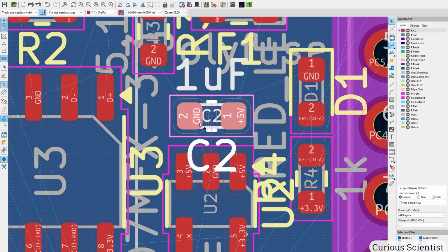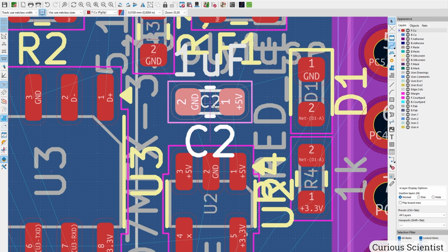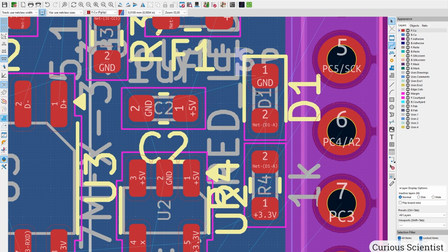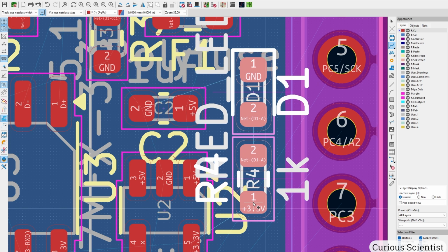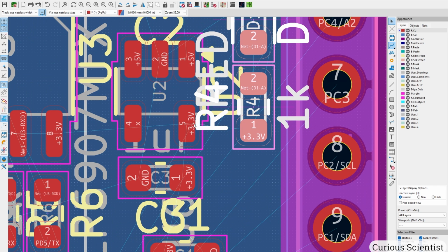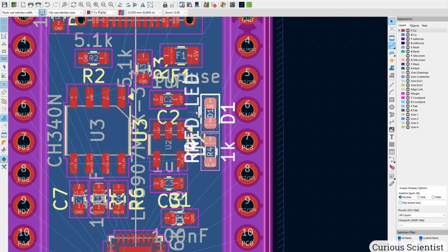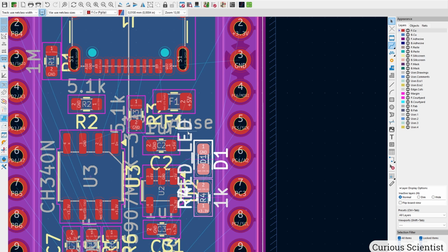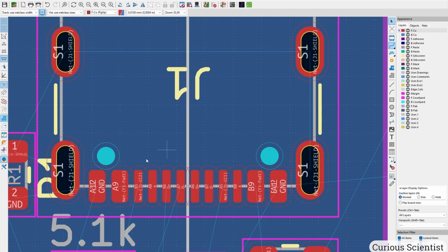And then I said that I want to route the trace here, so I brought this a bit up so I have space, and then I might be able to bring this also somewhere a bit more down, so I have 3-volt pins together, and I can create an island here. So this should be something like this. We can start routing things here.